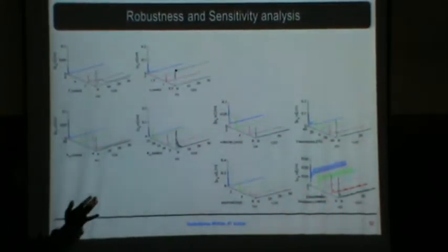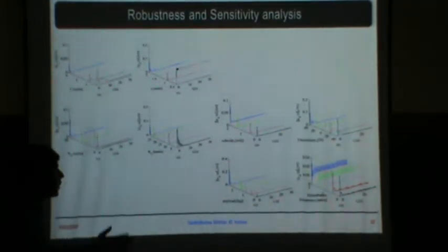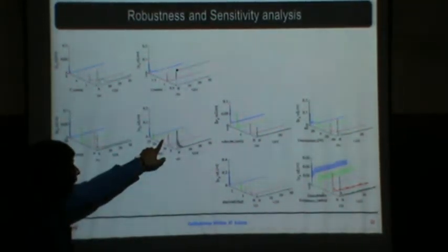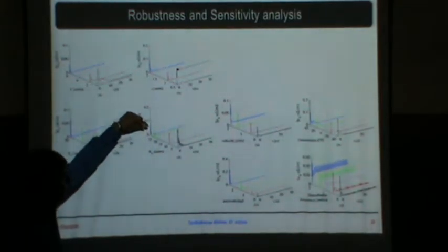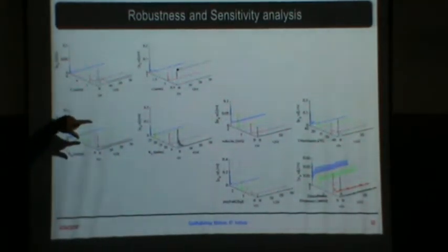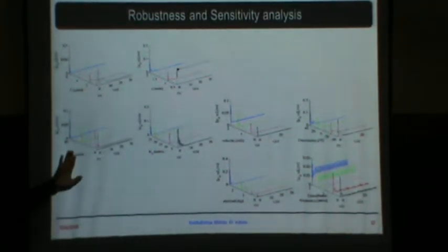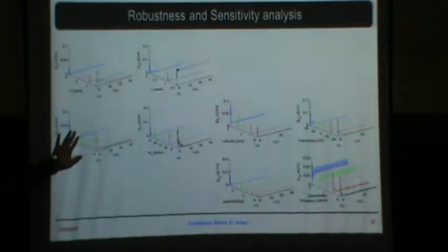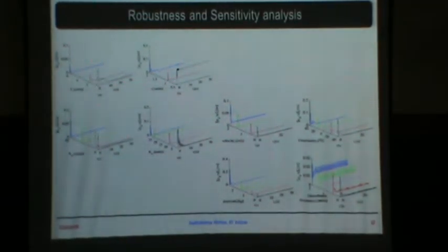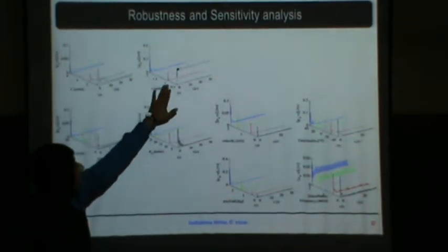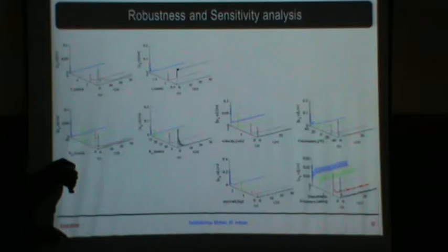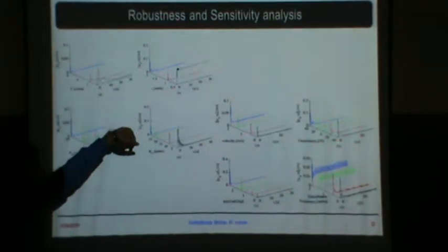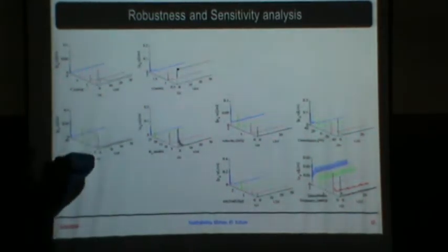If you keep on increasing, you can see that up to 15 it is okay. After that it is very narrow, but more control activity will be involved. Similarly, the observer gain is not so much different, as we have seen even without and with uncertainty. But the gamma is having a problem. If you take gamma as 0.5, indirectly it is the square root. If you take gamma as 2, indirectly it is the square.